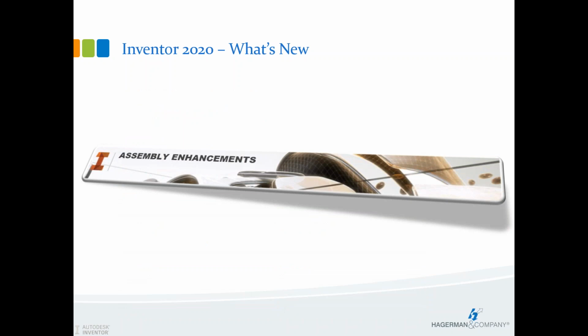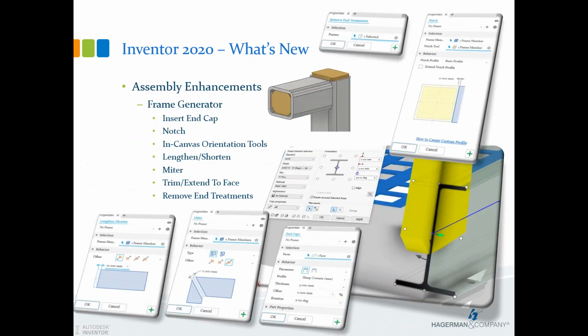Some of the assembly enhancements we're going to take a look at today are along the Frame Generator area. If you install the custom content library when you're installing the software, you're going to have access to this Insert End Cap command inside the design environment in assemblies. That allows you to insert an end cap and attach it with an offset on the outside of the face, or insert it inside the member that you're putting the end cap on.